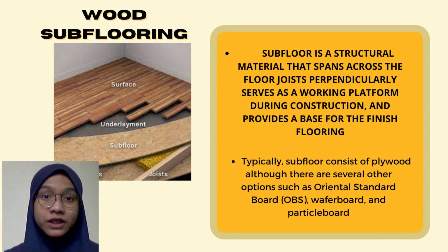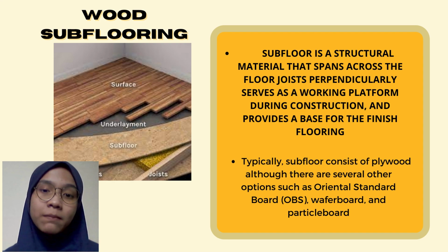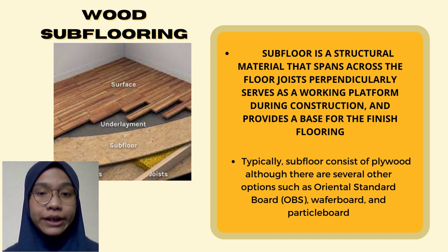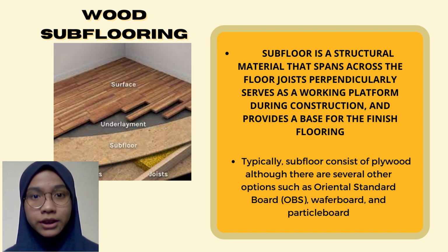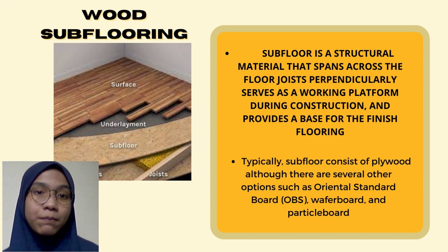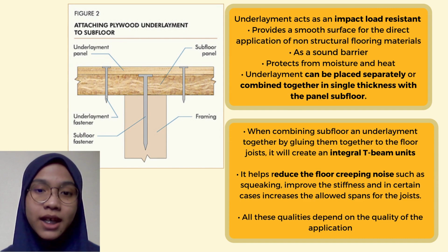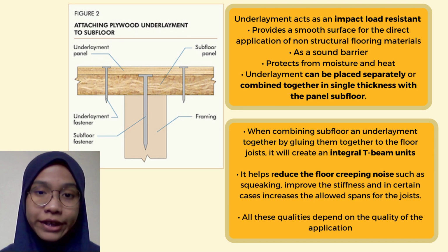So now we move on to wood subflooring. A subfloor is a structural material that is put across the floor joist perpendicularly, and it serves as a walking platform during construction. It also provides a base for the finishing of the flooring. Typically, the subfloor consists of plywood, although there are several options such as OSB, Oriented Strand Board, Wafer Board, and Particle Board. To explain how subflooring works, we must understand the system of this subflooring.